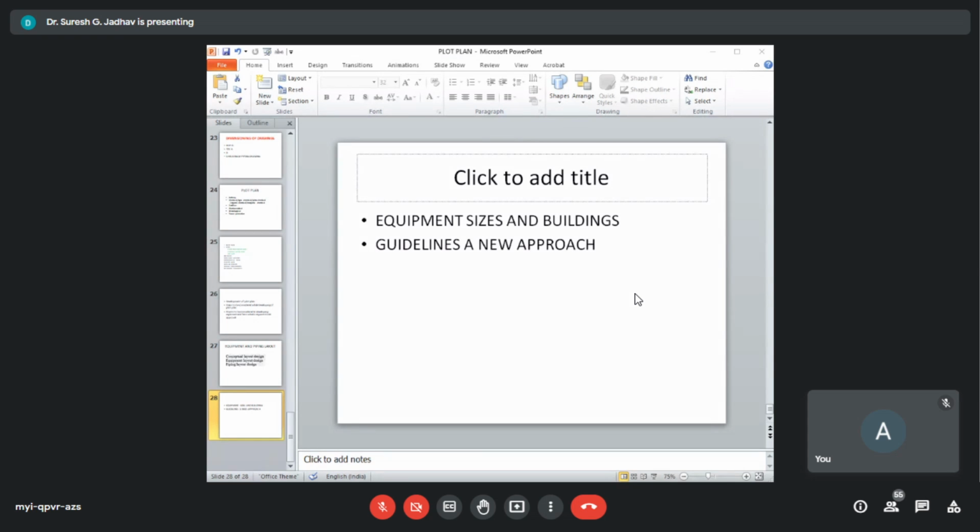So that kind of drawing sheets we can use for equipment layouts or unit plant drawings. Now we can place the north arrow at the top right hand corner of the sheet to indicate the plant north direction. The area above the title block is to be kept free for general notes.